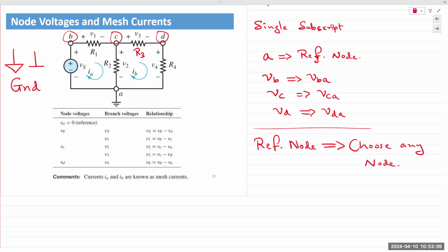But when you calculate the resistor voltages, they will turn out to be exactly the same value. Your node voltages might be different, but the resistor voltages will not. You can take a single example problem and solve it multiple ways, and your answers will all be correct. So, any questions so far?